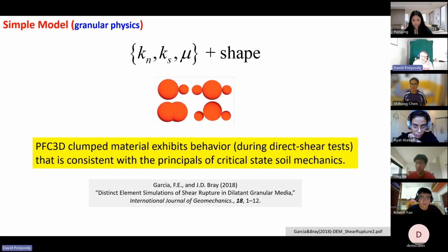So if you have even the linear model, if you have the shape in there, and notice they did not use discs. Discs and spheres will behave very differently than most sands, unless the sand is very, very spherical shaped grains. And most sands and most granular materials are not spherical. And so therefore you often need to put in the shape.